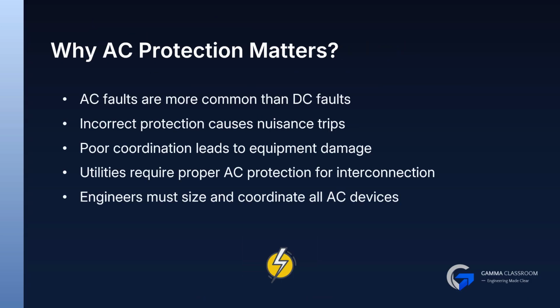AC protection matters because AC faults occur more frequently and propagate fast. Incorrect protection settings can cause nuisance trips, damage equipment, or even fail utility interconnection.